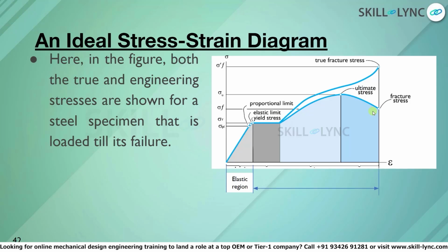In the elastic region, material has an elastic behavior, whereas in the plastic region, the material has a plastic behavior. Again, this plastic region is divided into four parts. We also should have this in mind that the plastic region is specifically for ductile materials. I mean, the four parts that it is divided into are for ductile materials and not for brittle materials.